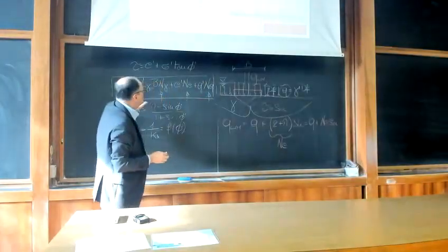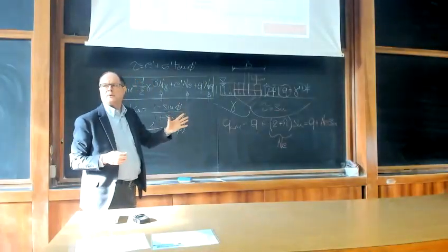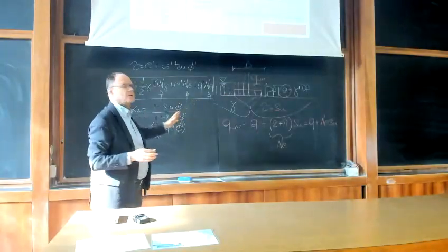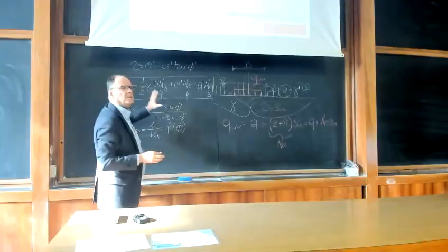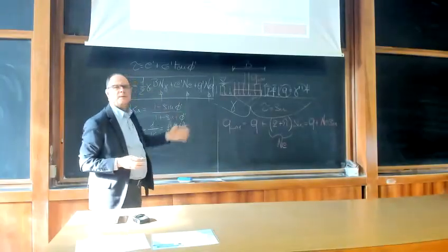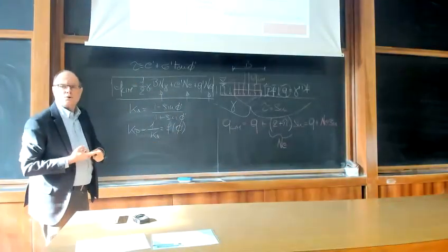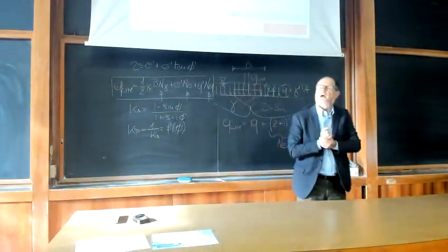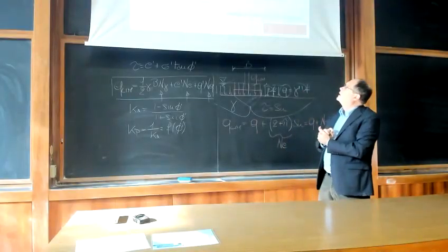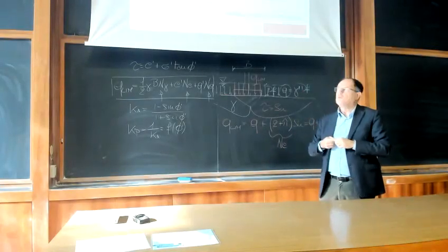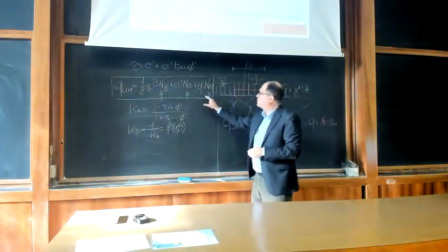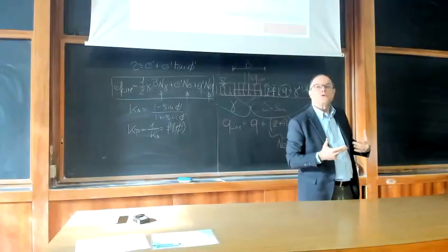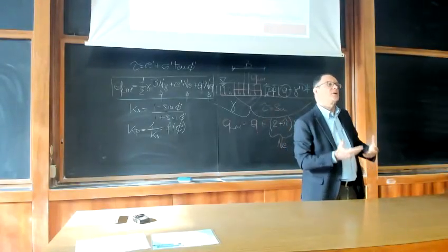And as you see, this is relatively simple. And we could have started just writing this expression and saying, well, you will consider the bearing capacity with this formula. Now, two things. One thing, we want to know where this formula comes from, and we have more or less understood that. Second thing, we have to know that this expression is valid and was derived for a general shear failure mechanism, which is not the only possible mechanism of a shallow foundation.